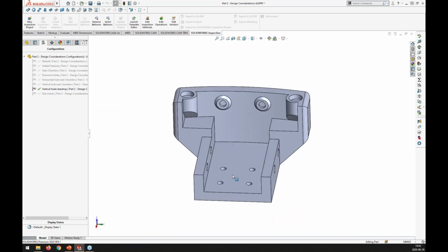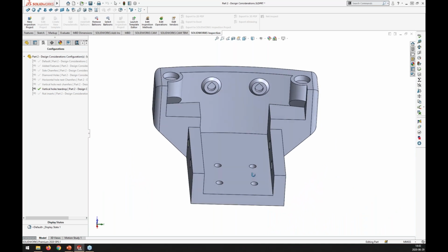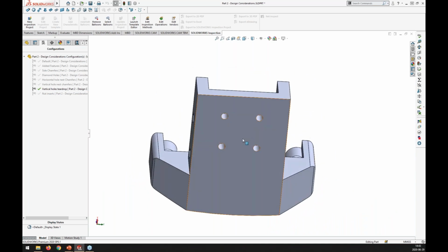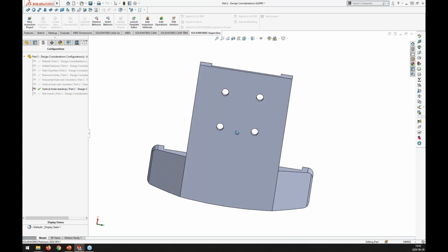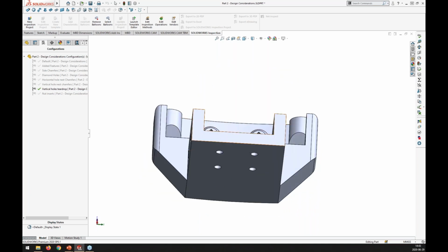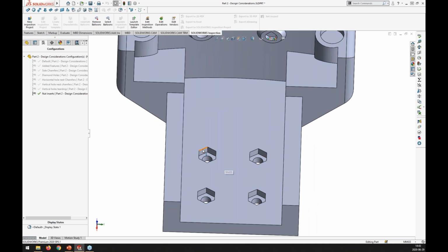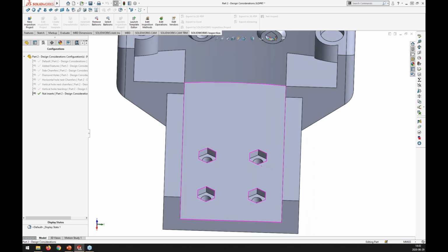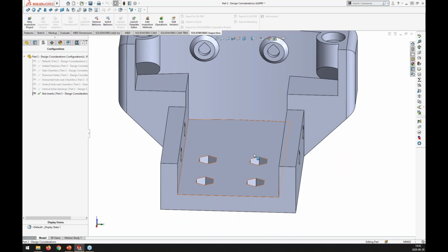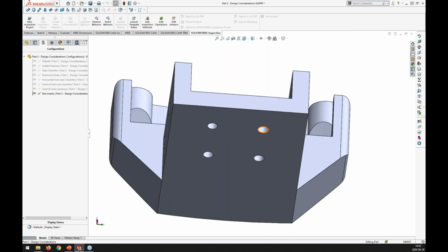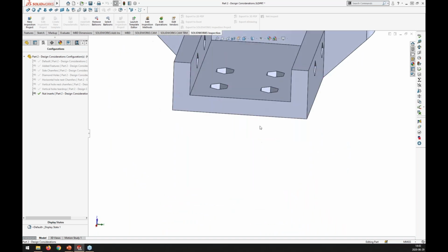And what we can do additionally here, let's say we would like to fix this part somewhere on the wall or to a different part right here on the back side, we can use nuts to have this stronger fixation. We design some slots for those, which in this case, those nuts can be inserted after the print and fastened from behind.